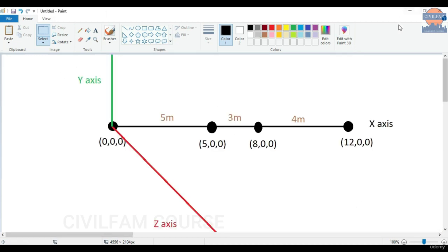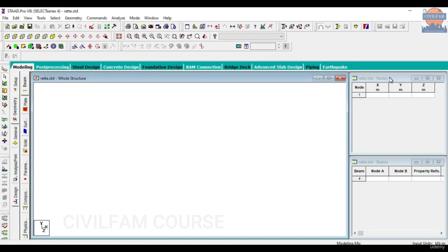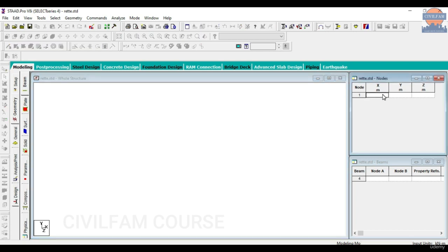So far, whatever beams we have worked with, we had always gone only in one direction, that is, only in the x direction by giving it values. Both y and z axes were left at 0. What I mean by that is, if I want to draw something, I always went like 0, enter, and then I give some value 5, enter, and then I give some value 6, enter, or something. This is always taken from this 0 comma 0 comma 0 point.